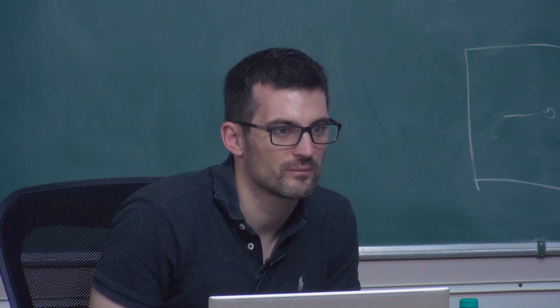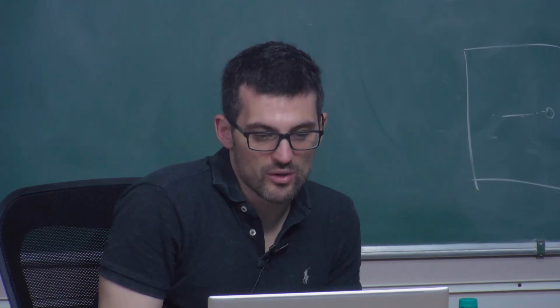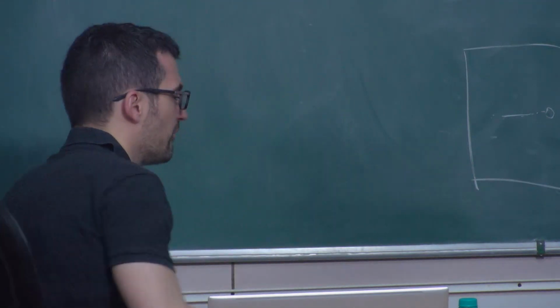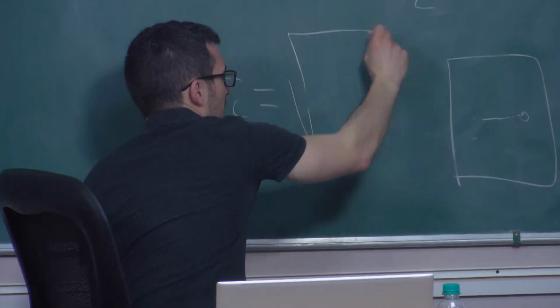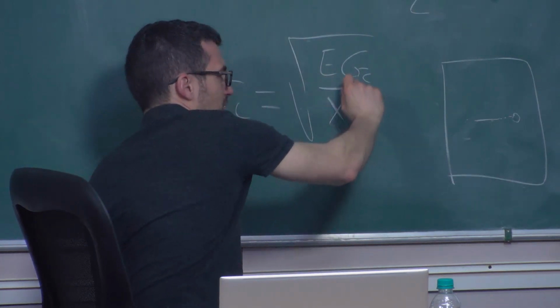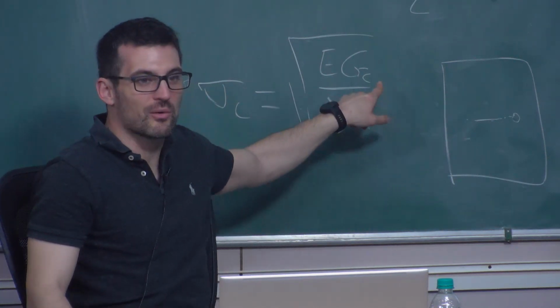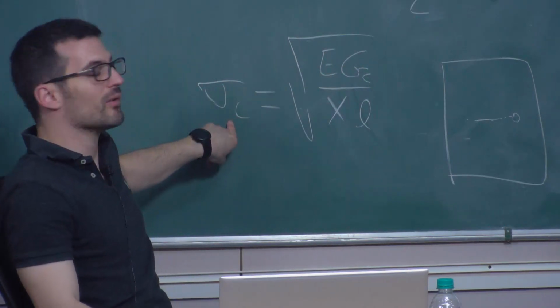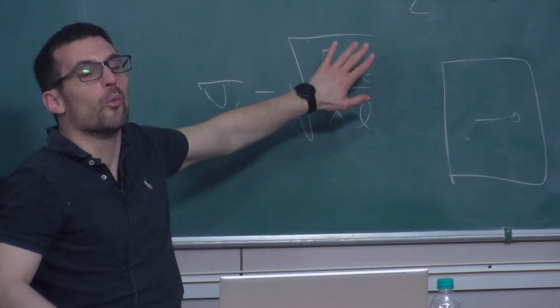Thanks. What about the length scale parameter? If GC is degrading, maybe that L is also a material property. Yes, so if you remember the equation for the relationship between the strength sigma and the other parameters, you have E, you have GC, and then you have L, and then some sort of constant factor. So it is true that by degrading the toughness, you are already degrading the strength. That's why you see this drop in the KT diagram.